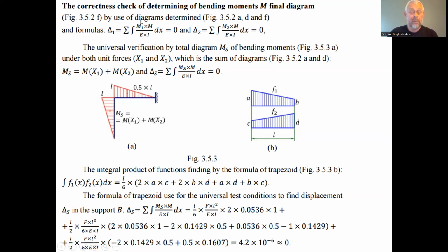If we assume that we look for the displacement not in the first force direction, uppercase delta 1, and not in the second direction, uppercase delta 2, but we consider the generalized displacement as an abstract concept, considering the superposition of the displacements in other directions of the proportional elastic mechanical system, each displacement is the total of delta 1 plus delta 2.